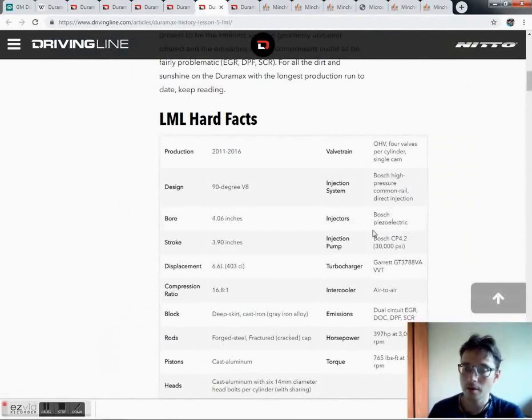They used piezoelectric fuel injectors, which are much faster than solenoid, so they allow up to 5 and even up to 6 fuel injections for one cycle, and that helps to make very precise control of combustion, and engineers can just match the pressure curve to the desired region to avoid very high pressures in the cylinder, to avoid excessive pressure rise rate, and also to keep the engine efficiency, fuel consumption, and engine emissions in the desired range.